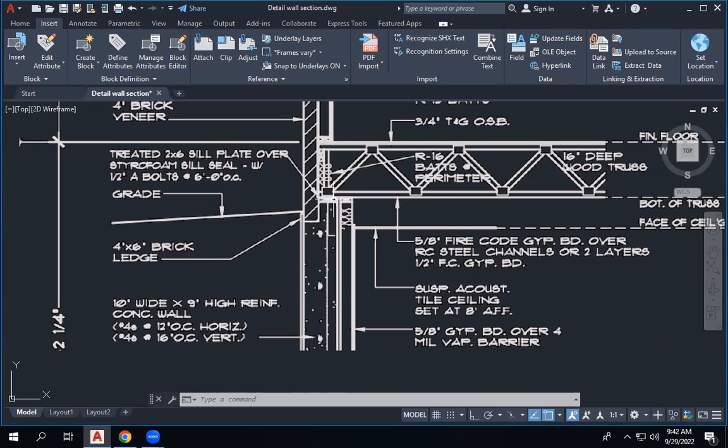We have concrete here because of this truss. You said wood truss or steel? I think it's wood then. Yeah, it's a wooden truss. It's supported on the concrete because you cannot support it on this insulation and this timber stud, because there will be a big load coming onto this truss, so it will be transferred to the concrete.